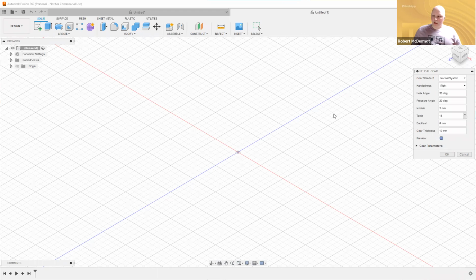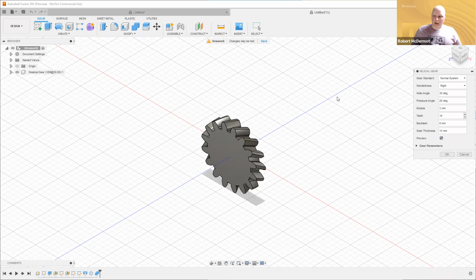Well, a helical gear has its teeth that are kind of at a slant. And if you put two at a 90-degree angle to each other, the slanted teeth allow them to roll on each other and transfer the motion from this direction to this direction, right?